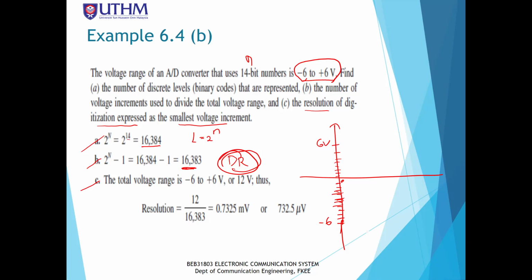So resolution is equal to the range of voltage, 6 volt minus -6, divided by the dynamic range, 2 power of n minus 1.